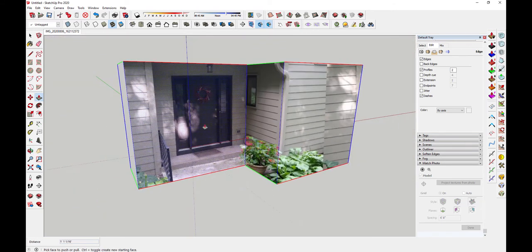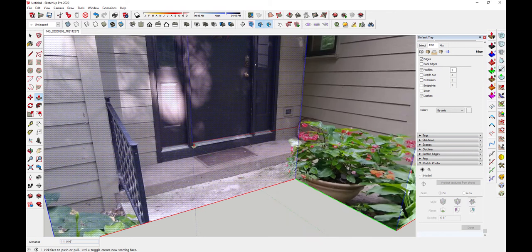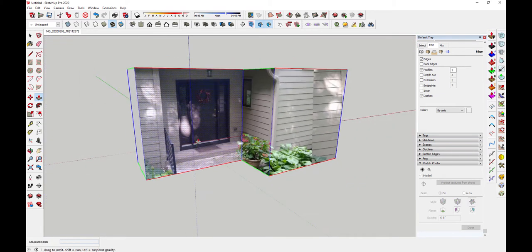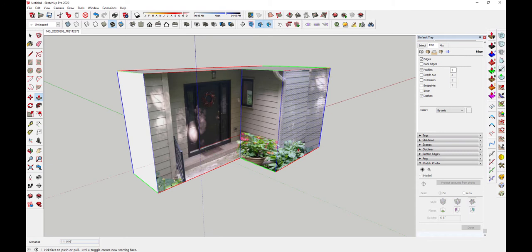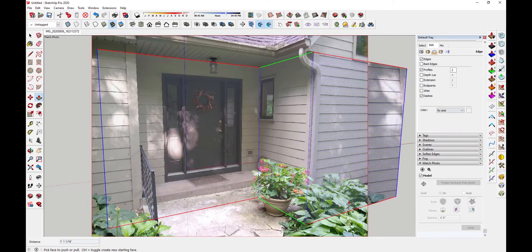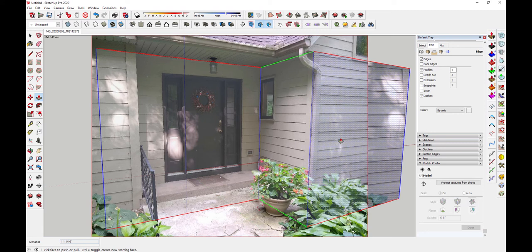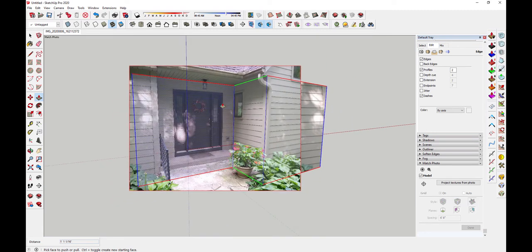Also, when I started my modeling, I did it on the origin, and I put my origin here in the photograph. You want to start with the origin and keep it in the origin. In other words, I would not draw this face out here with this photograph. It is misleading. You'll never get it. It'll line up kind of funny. You'll say, what's going on here? Always start with the origin and push-pull out, push-pull up, or draw rectangles from the origin so that it's all square.